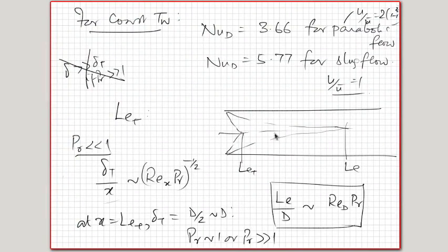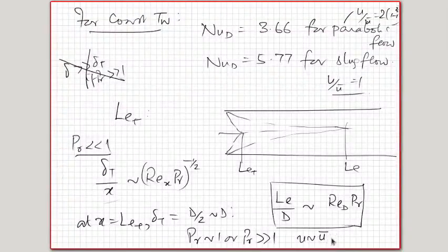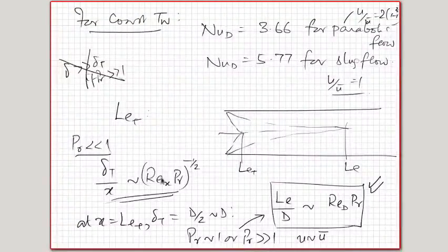So in the entire cross section or in the entire thermal boundary layer, the velocity u is always of the order of u bar and never u bar multiplied by delta_T by delta, which is a very small number in the case of flat plate boundary layers. Here it will be of this order, and therefore the same expression will also hold good for Prandtl number of the order of 1 or much greater than 1, because the dependencies don't change between Prandtl number much less than 1 and much greater than 1.